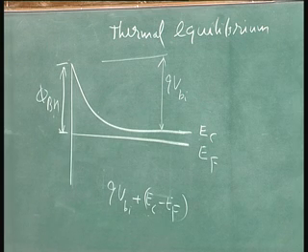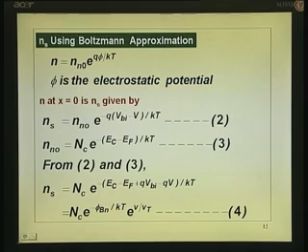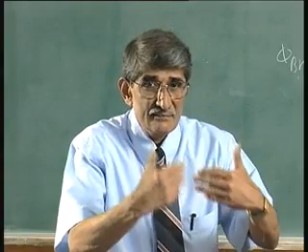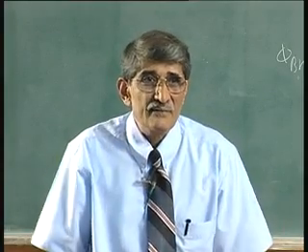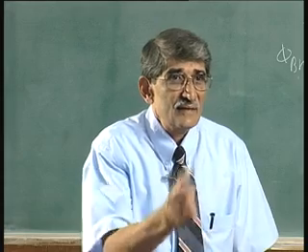Now, so that is what we have done. I have taken all these three quantities together and put them as phi Bn. So, e to the power minus phi Bn by kT, and this minus and this minus together become e to the power of V by VT. Now, you can see the whole thing has become simple. These are the electrons which are capable of crossing the barrier. So, they are present at the boundary there, and they will be impinging on the surface with a velocity v of x in that component.